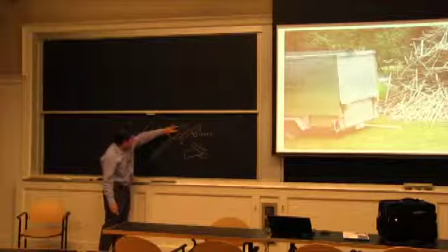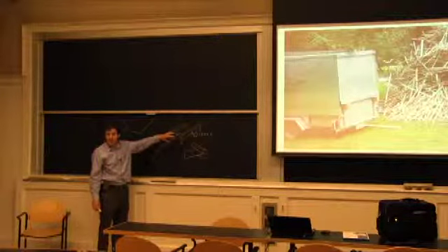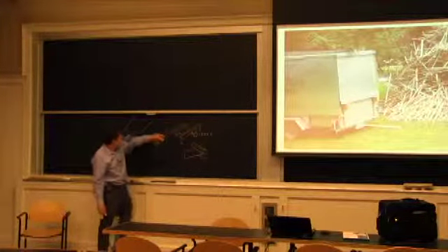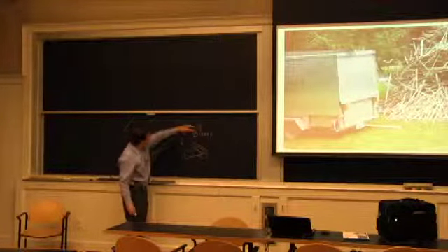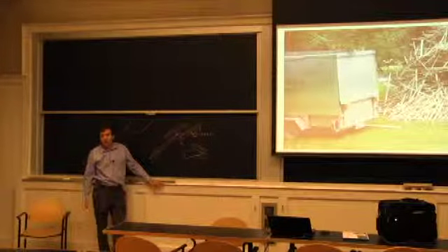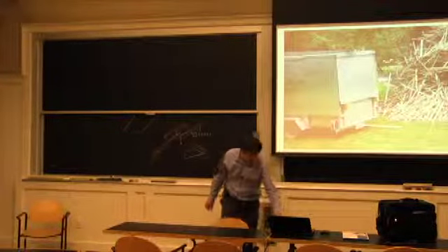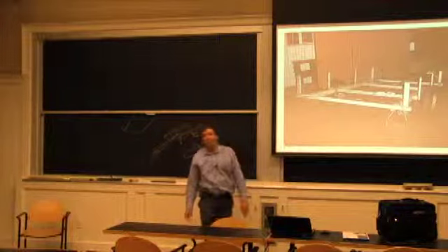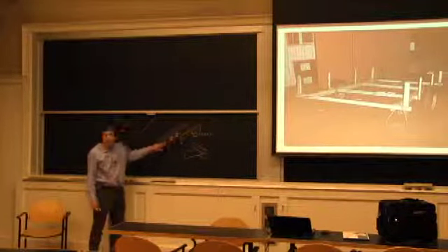So if I start changing the section size as I'm moving along, I'm adding to the number of pieces of metal to put together. I could do the same here. For this member, the highest load is in the middle. I could say I'm going to strengthen this section. But it's not always practical. I mean, in the end here, I only had beams, and you saw them on the floor, and I wanted to put them together. I didn't really want to have to make longitudinal connections or lap joints just to optimize everything as if it was an airplane. It's not an airplane. So the practical way to make this stronger is to make the whole beam stronger.